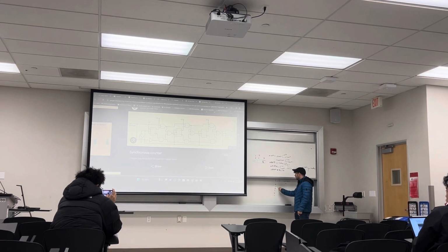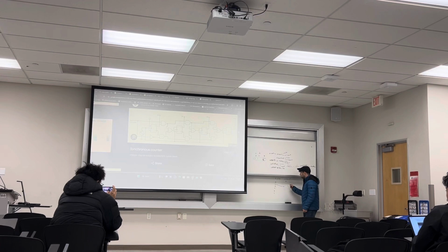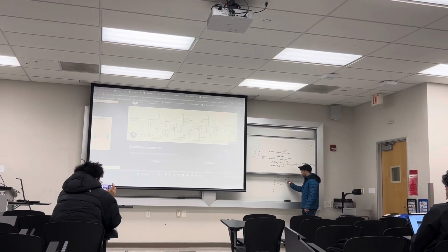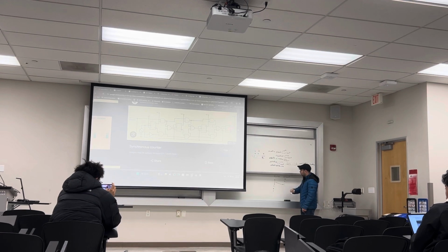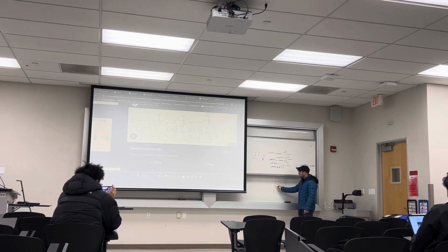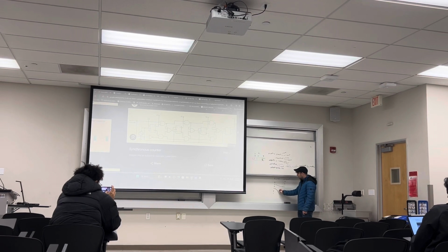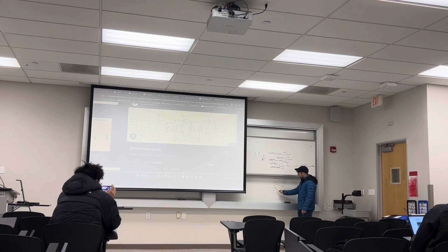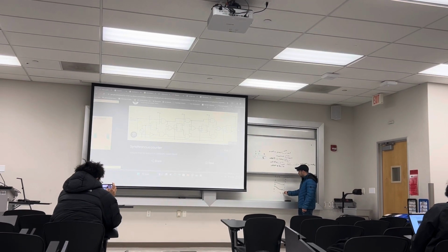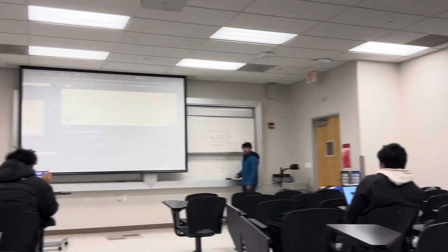So it will change on the next clock. So here it will be 0, and then at this location it will change to 1. Again, it's 0, so it doesn't change, so it will be 1. Then it's 1, so at this next step it will change to 0. And then it's 0, so it will be 0 again. Okay, this is the structure of the second stage.